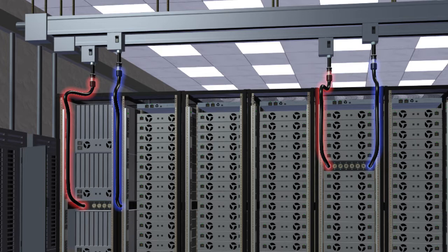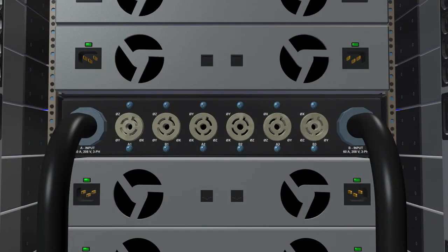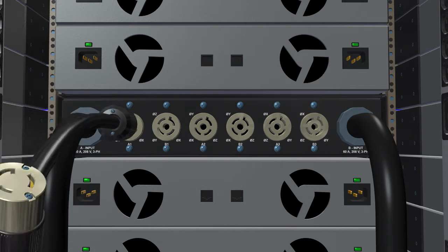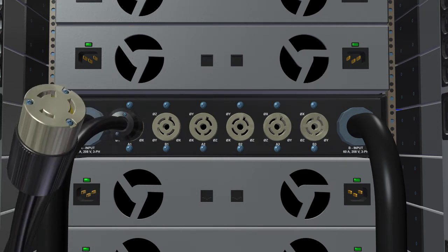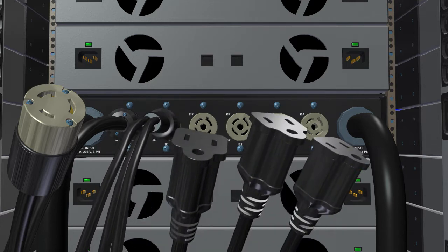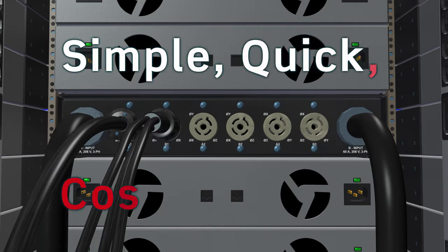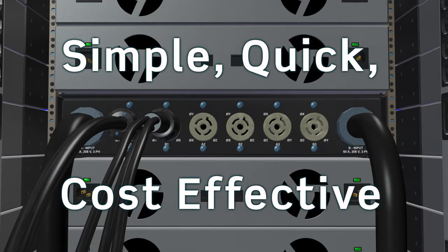All other needed power changes are made at the Z-PDS system in or at the rack, using low-cost plug adapters which are part of the Z-PDS system. The plug adapters insert into the outputs of the Zonit power distribution units and change the output receptacle to meet whatever power requirement is necessary. Simple, quick, and cost-effective. This is more efficient and safer than making changes at the panel board or inserting new tap boxes in the busway.